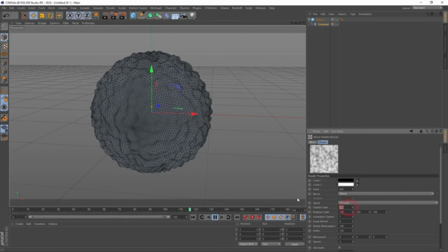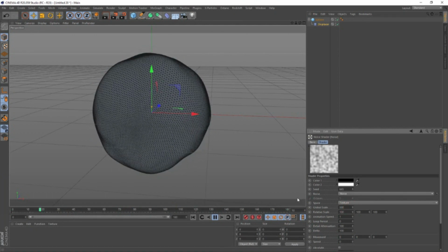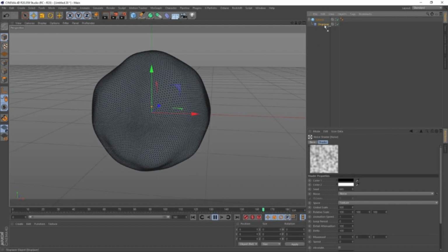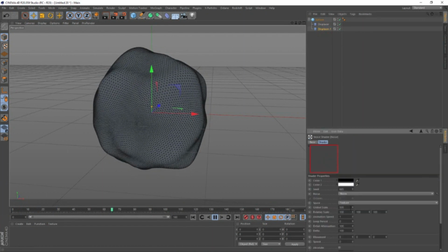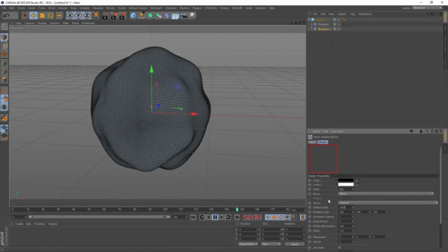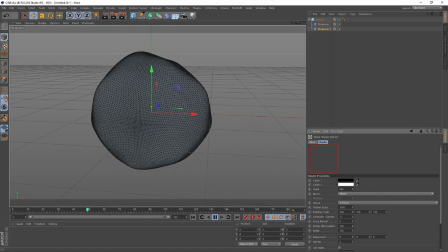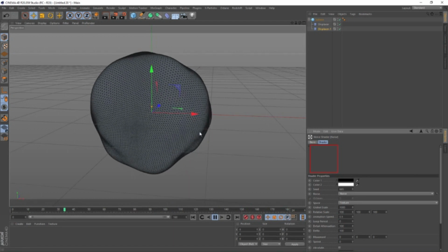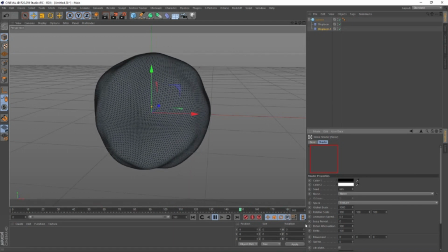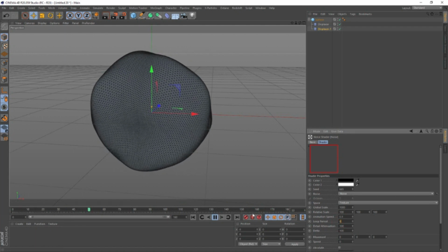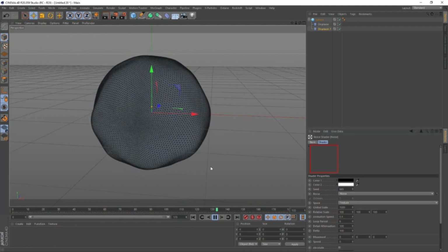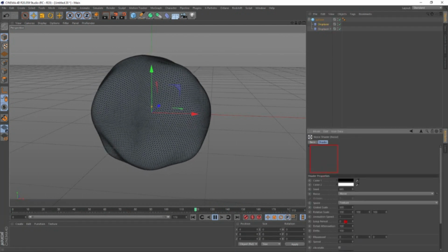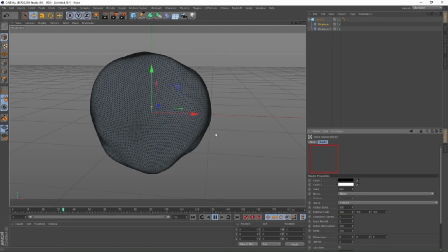Now we have the base animation, we're adding extra scale, duplicate once again, one more displacement with big global scale and lower animation speed, so we have more complex morphing. We set loop period to 6 and decrease 1 frame because we have 30 FPS, and going to another displacer, going to loop period 6, and we have loopable animation.